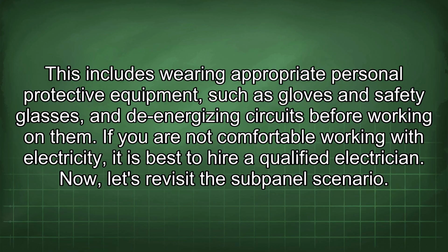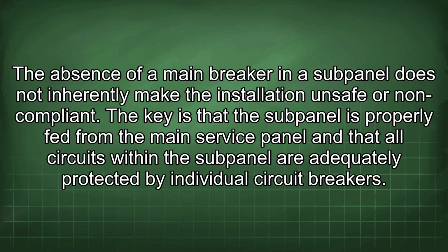Now, let's revisit the subpanel scenario. The absence of a main breaker in the subpanel does not inherently make the installation unsafe or non-compliant. The key is that the subpanel is properly fed from the main service panel and that all circuits within the subpanel are adequately protected by individual circuit breakers.